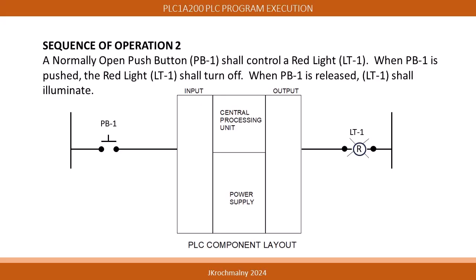Imagine what a programmable logic controller is and what it does. It can be considered a complex relay device that, based on the status of its inputs, commands its outputs on and off. When PLCs are used for device control, conceptually, they will always be installed between their inputs and their outputs.